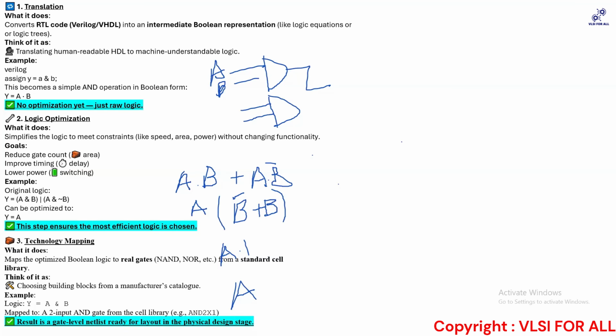For an AND gate itself, there can be various flavors. If you have ever opened up the library, you know that you don't have just one library. These libraries are present across various corners in your design: your SSG, FFG corner, typical corner, your different PVT. That's a very different vast topic, and I'll explain as we go further.